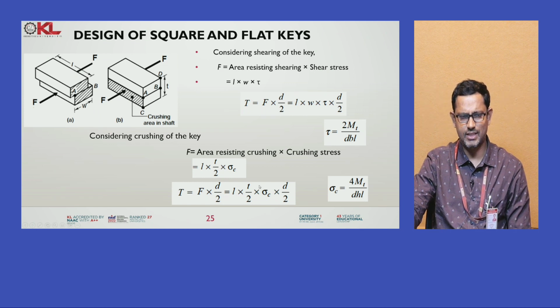So while designing keys, we have to consider first the shear failure, and second the crushing failure. If the given value satisfies both of these equations, we can claim those values are correct.